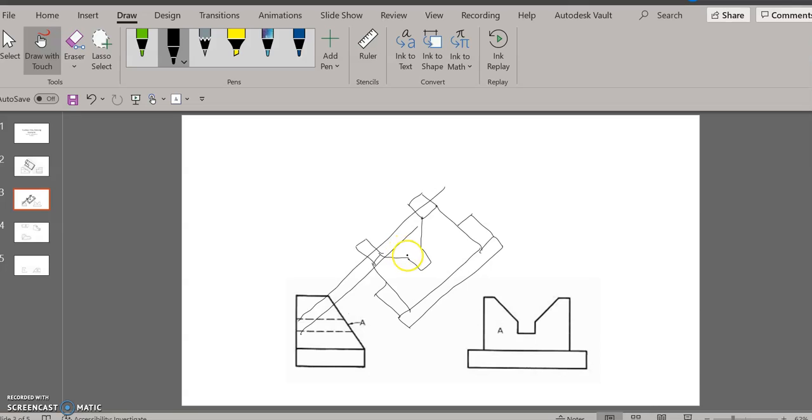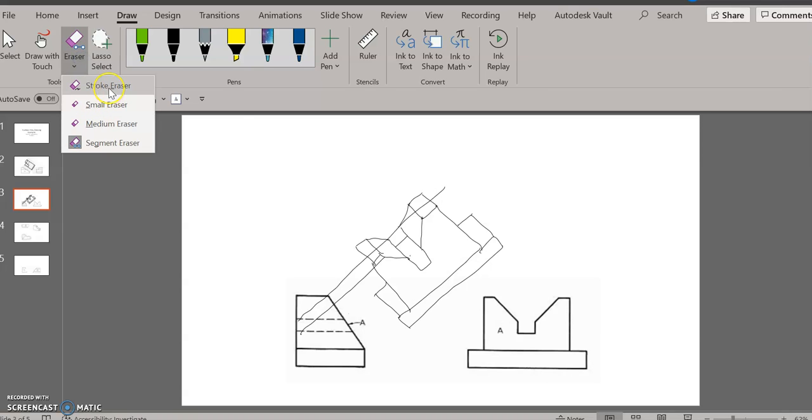This is going to go straight back because that's where the top of the slot goes. And that's going to go all the way to that line. That's going all the way to that line. And then I can go ahead and connect my corners here and here. And you'll see that the angle looks a little bit different because I'm looking at that surface at an angle. So I need to go ahead and do some trimming and erasing. So I'm going to trim here and here,